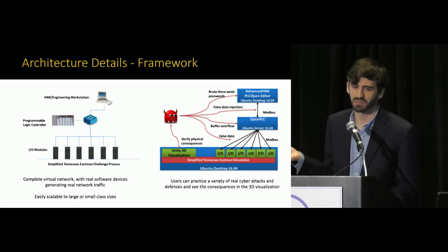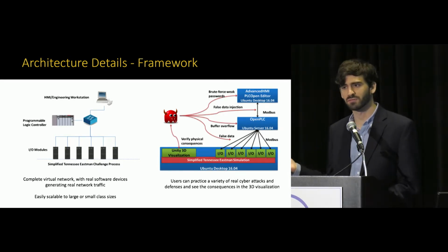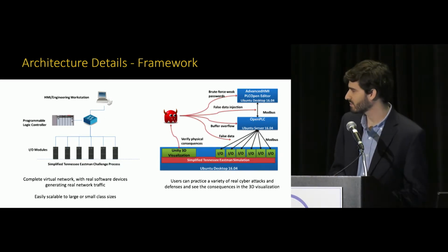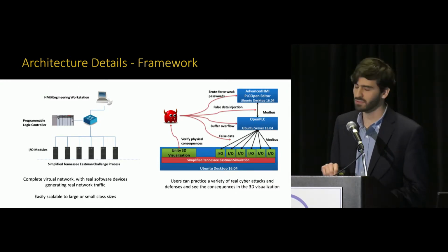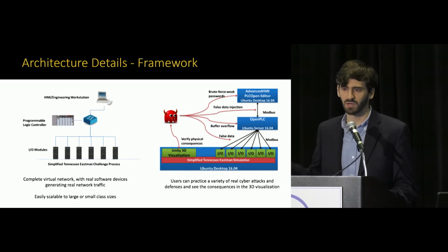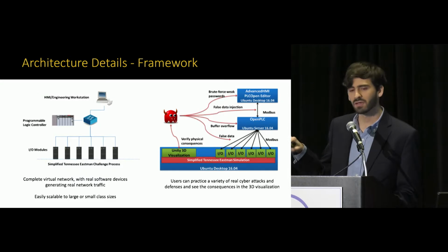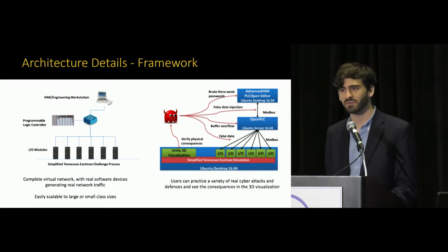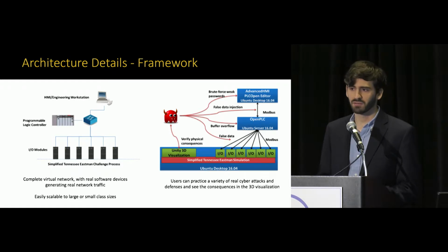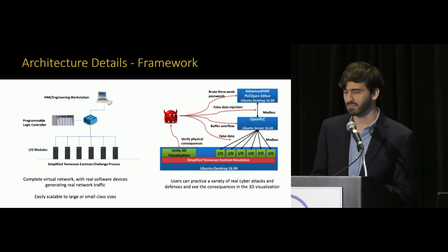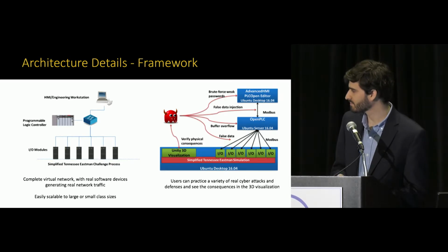That PLC also has a vulnerability in the Modbus library. So if you're really into the technical details of IT security, you can practice your buffer overflow exploits and get a shell on the PLC and mess around there. And finally, that PLC is talking to some simulated remote I/O, again over Modbus, where you can practice that man-in-the-middle attack. All of this, again, is being visualized in this 3D game engine. So trainees can understand and appreciate that if I send false data to the HMI, I can hide my attack that's causing the reactor to explode or other physical consequences.